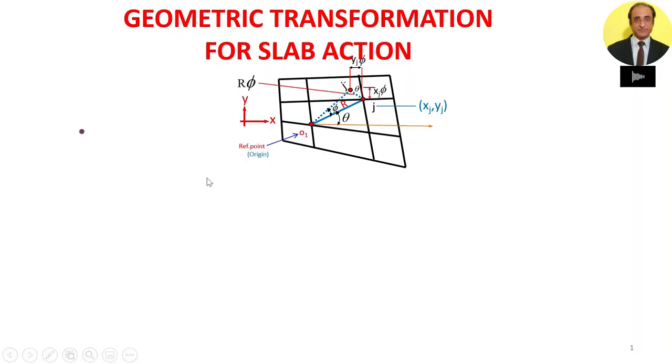So in the previous lecture, we had begun treatment for considering the rigid diaphragm action of the floor slab. Basically, the floor slab introduces a compatibility condition that any 2 points lying on the floor slab will undergo translation and rotation in such a manner that the relative distance between the 2 points does not change. That is, we can consider that the floor system undergoes a displacement like this. So we can view it that the entire floor system is undergoing rotation about an external point like this.